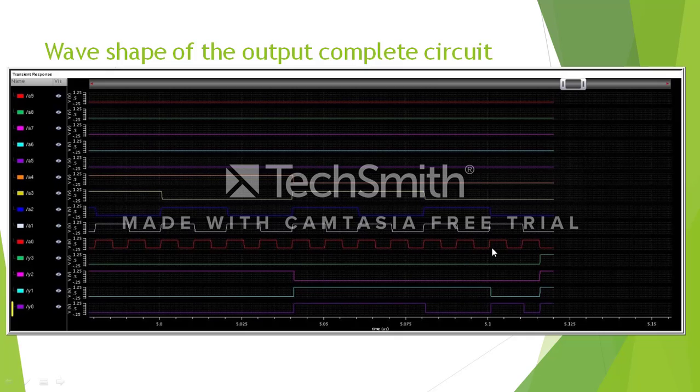We know that if every input pin is low, then the output will be high, which is shown here. When every input is low, then the output pins Y3, Y2, Y1 and Y0 are showing active high. And when the input pin A0 is high, then we can see that the output pin is 0 0 0 0, which is indicating the active input pin A0.